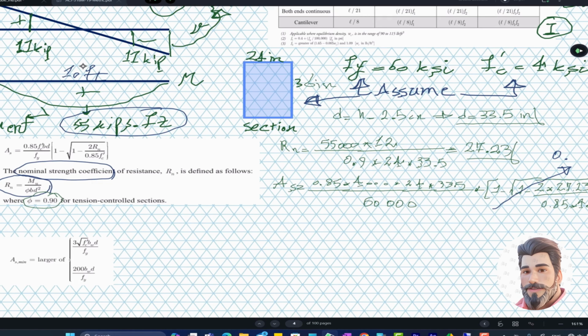Notice that, of course, this value must be greater than the minimum value of the longitudinal reinforcement set by ACI. Otherwise, the minimum values calculated in the proposed formulas will be used.